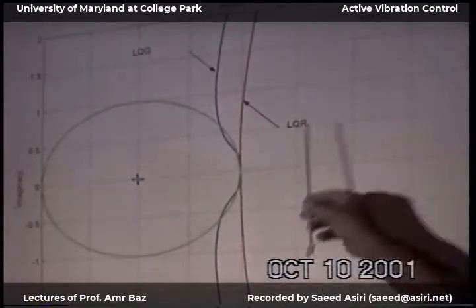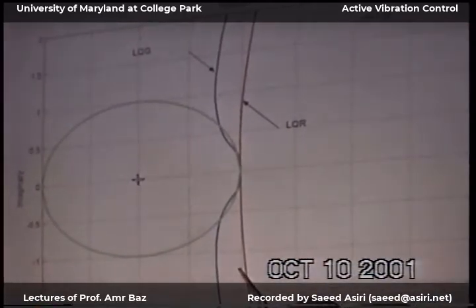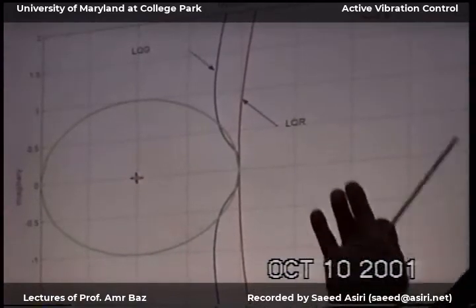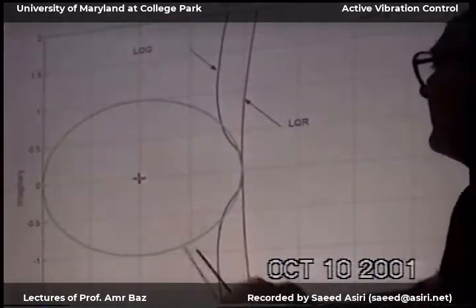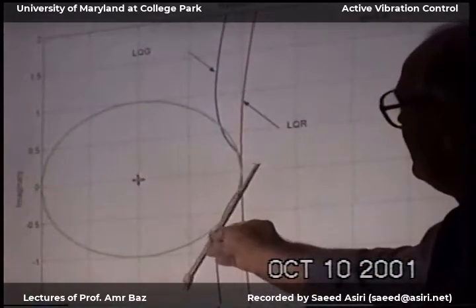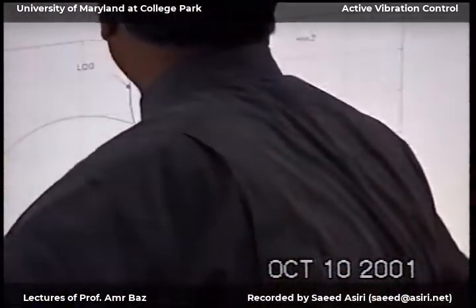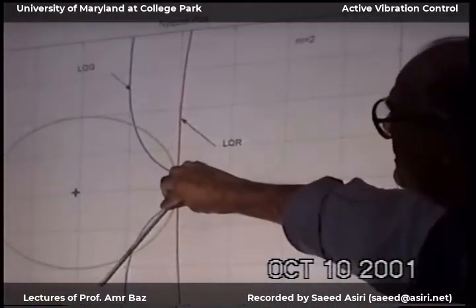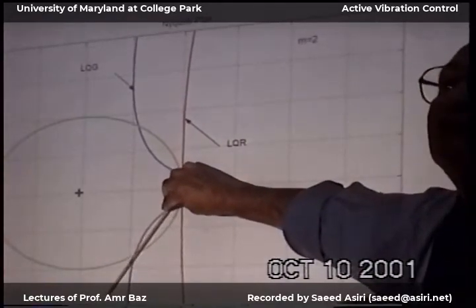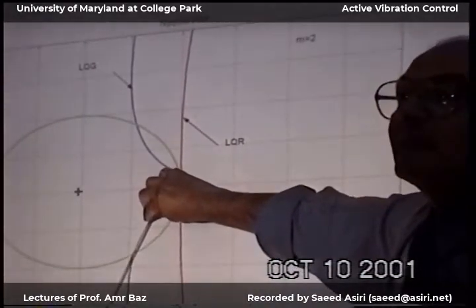We're saying now, if I am in this case, the LQR, then it takes me 90 degrees of delay in the system to bring it to the unstable zone, which is 180 degrees, minus 180. Here, it will take much less. And when you have more uncertainty, then you cross at this point. So the amount of phase margin is no longer 90 or 80, now it's maybe 60. And then more uncertainty brings us more inside.